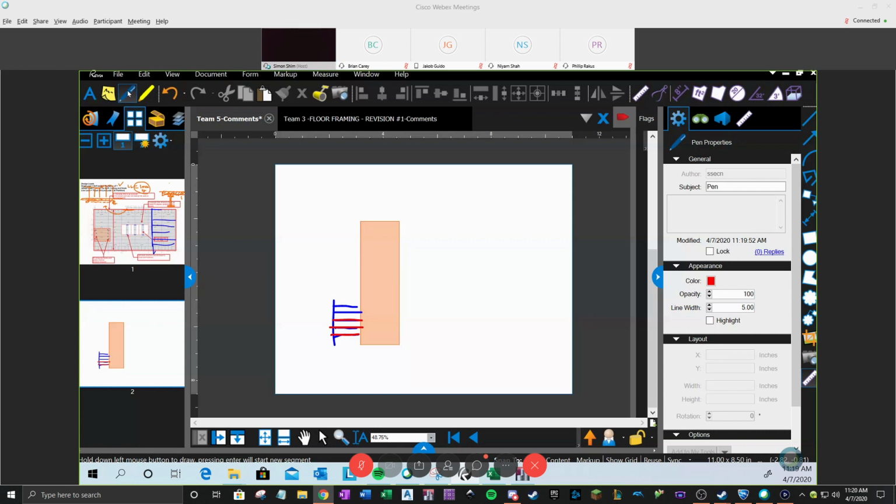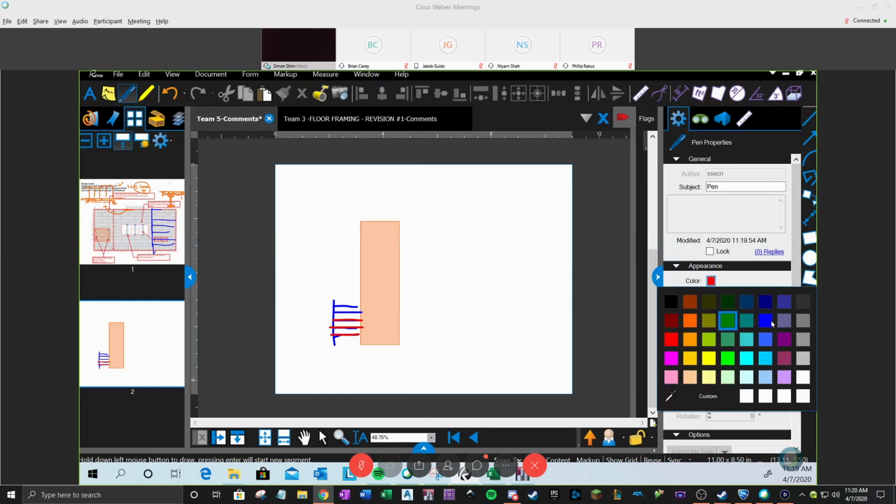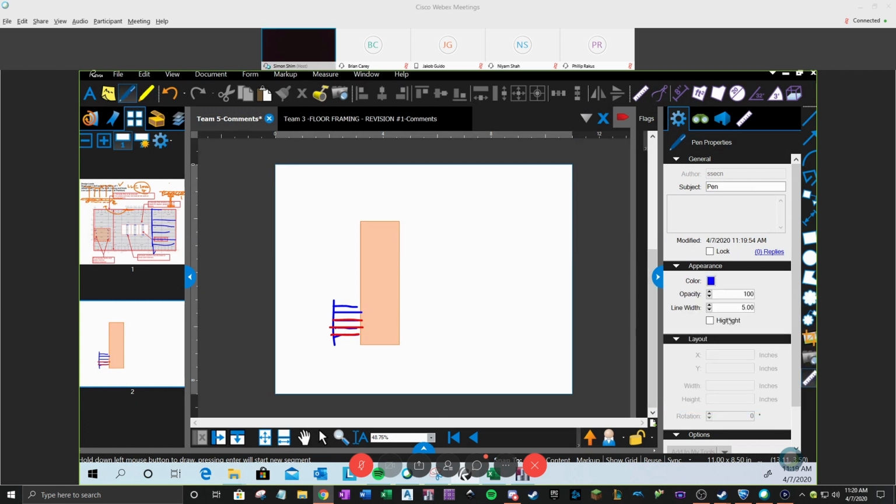And where the floor has a concrete slab, the contractor is going to erect the enclosure, exterior enclosure first. This could be curtain wall or block wall, right? So this is the general sequence of a high-rise building.